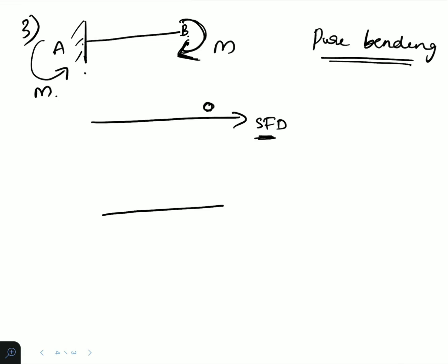Okay. So here, the bending moment diagram: the upper side we are putting positive, the lower side we are putting negative. Because of this force, the moment will cause it to bend like this. So this moment is acting like this, so it will be a hogging case. So it will be negative, and we have to draw it on the lower side.